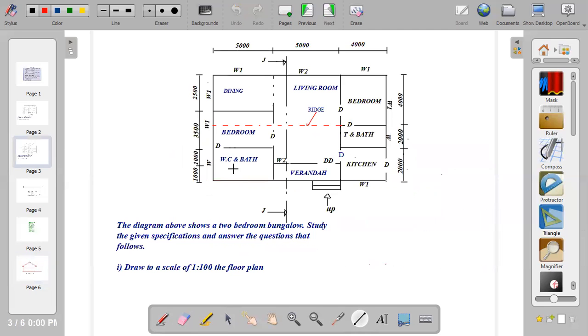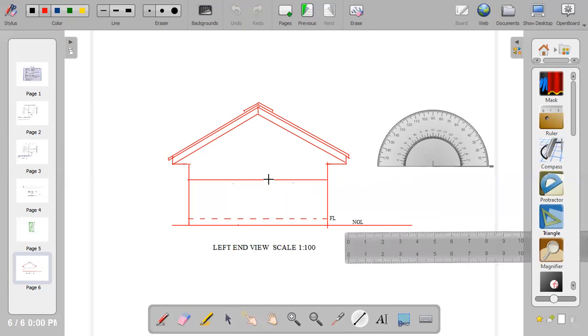Let me see the position. It's in between. So I don't need to project a line. It's in between. I'll just carve it out in between this by measuring 1002. I'm assuming this is 1002 by 1002. Then in between 2005, I have another window which is 1002 height by 1002 width.